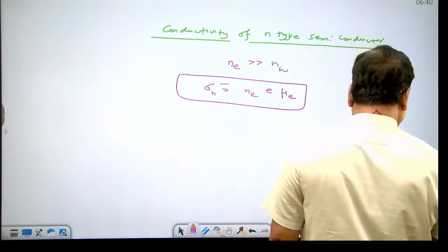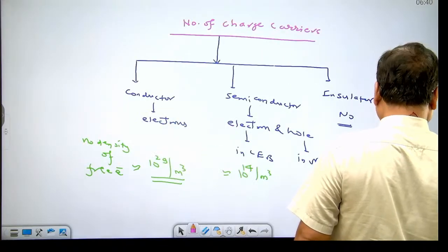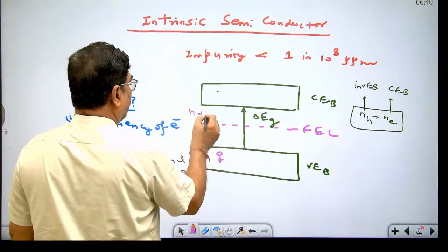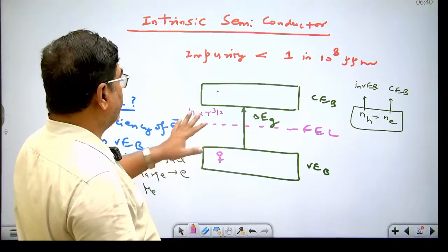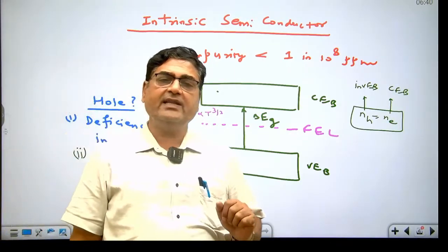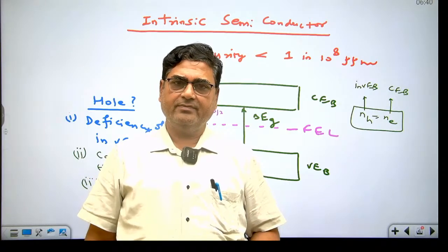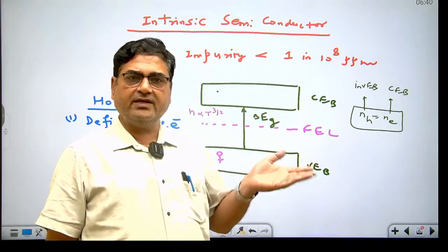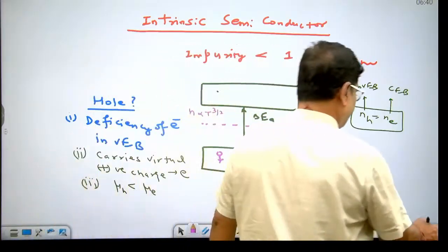And dear student, remember the number of charge carriers in intrinsic semiconductor moving from valence energy band to conduction energy band is directly proportional to temperature to the power 3/2. That's why at zero Kelvin, intrinsic semiconductor behaves as an ideal insulator, while at some temperature conductivity starts. With the increase in temperature, the conductivity of semiconductor increases because here both holes and electrons remain present.